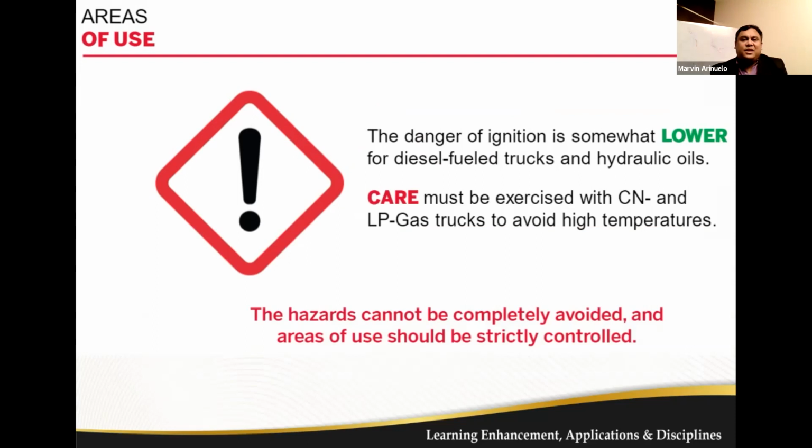Care must be exercised with CNG and LP gas to avoid high temperature near ovens, furnaces, and similar heat sources. Special safeguards in the design of some types of gasoline, diesel, and LPG trucks help to reduce this fire hazard, but the hazards cannot be completely avoided, and areas of use should be strictly controlled.